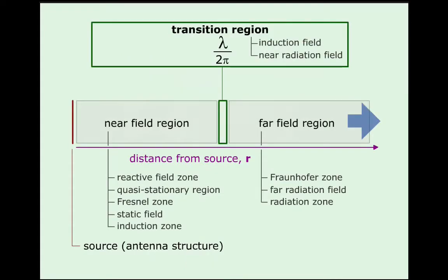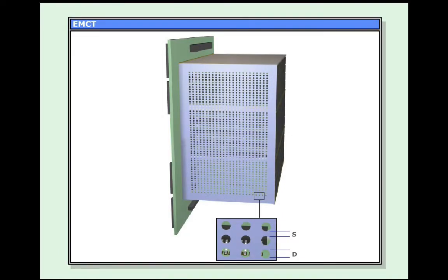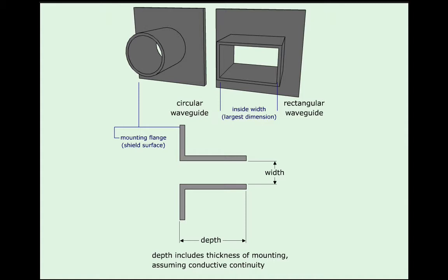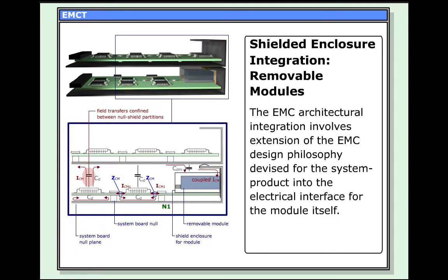You'll begin with a look at the broad concepts of how shield structures function in terms of losses and shielding effectiveness. Next, you'll examine the effects of the incident wave impedance on the performance of a shield. Then, you'll investigate the effects from gaps, seams, slots, and perforations. You'll learn how to use waveguide apertures in a frequency mode below cutoff, and study apertures, gaps, and perforations as phased array structures. Then, you'll learn how to use localized shield structures.